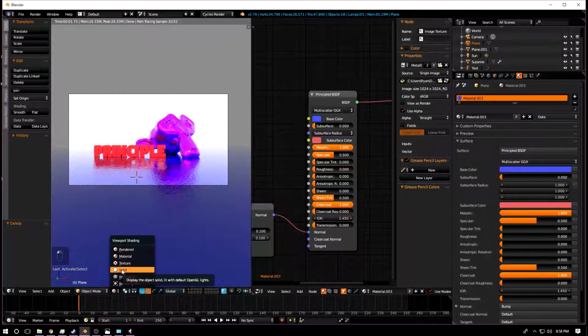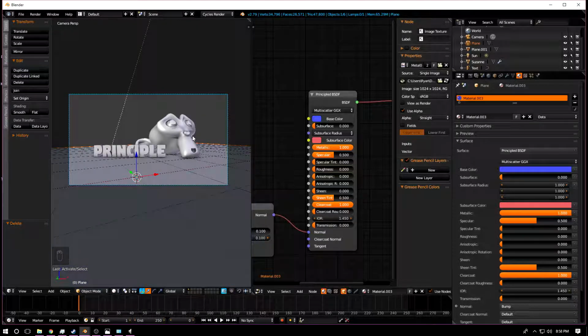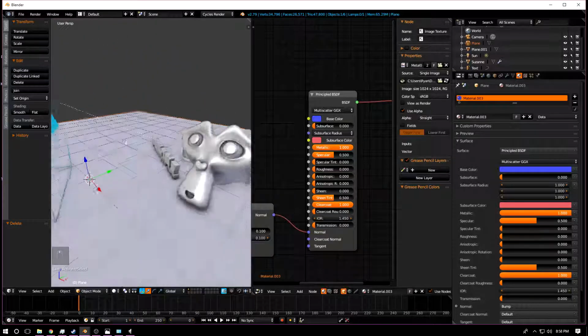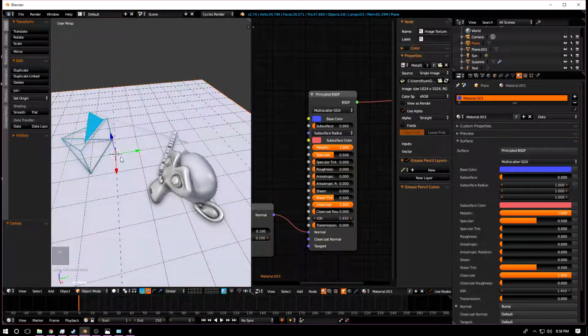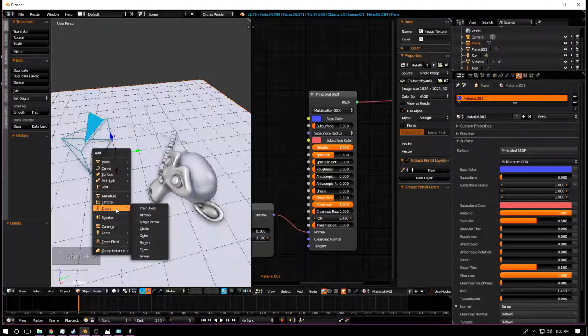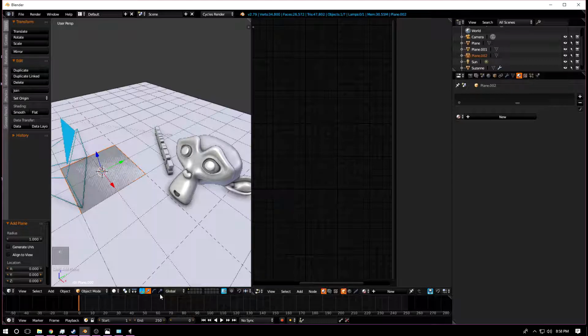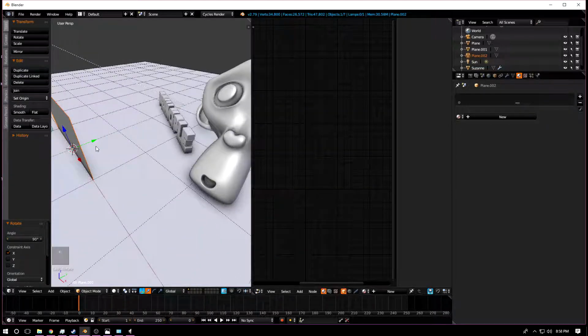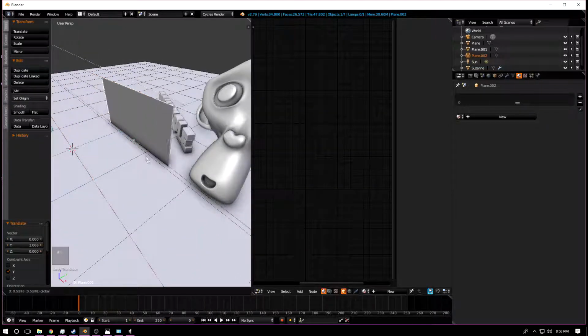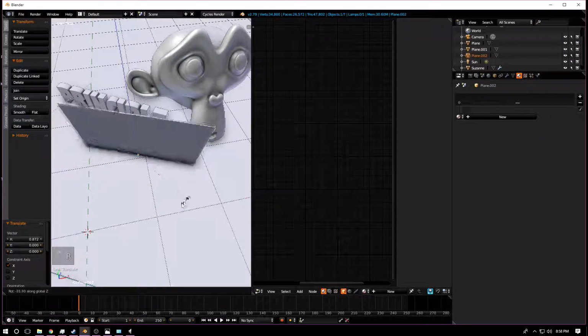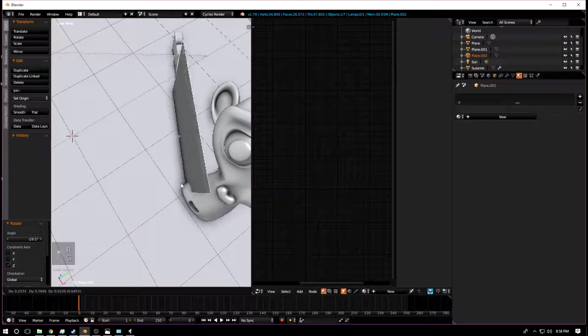First, I'm actually going to add some depth of field. That will smooth out the edges and the textures. Depth of field really adds some realism to your scene. So to do this, just press Shift A, go to Mesh and add a plane. I'm gonna rotate X 90, and then I'm gonna move it so it's pretty much blocking the main part of the view.